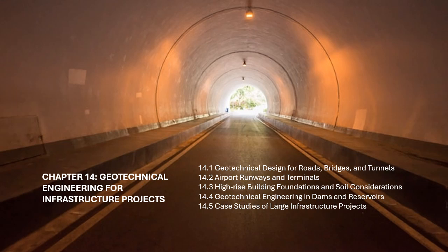One World Trade Center, New York, USA. The foundation of One World Trade Center involved deep drilling into glacial soils and bedrock. The design included large-diameter bored piles to ensure the stability of the tower, which is located in an area with complex soil conditions due to its proximity to the waterfront. Geotechnical engineers also implemented extensive dewatering systems to manage the high groundwater levels.